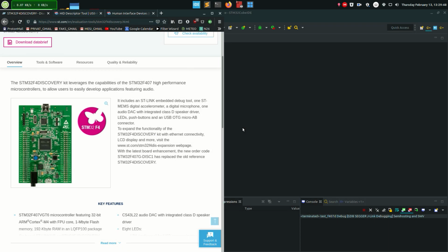In this one we're gonna continue on the topic of USB peripheral. Last time we checked out how we can use the USB peripheral of our microcontroller to create a virtual COM port, a serial port, so you don't need to use an external USB to serial converter, which is very handy. So if you have your USB and you want to create some kind of keyboard or a custom controller, then today we're gonna talk about that.